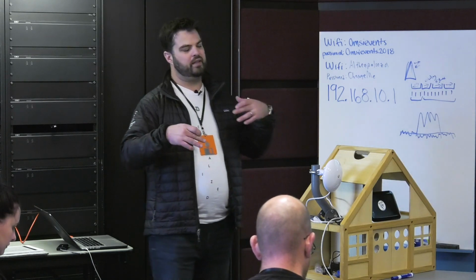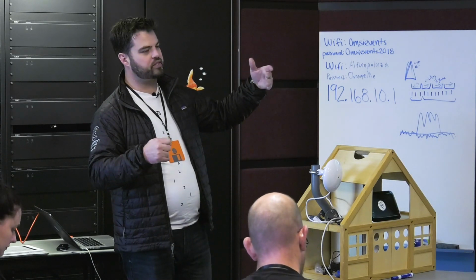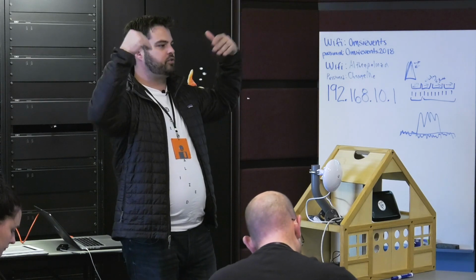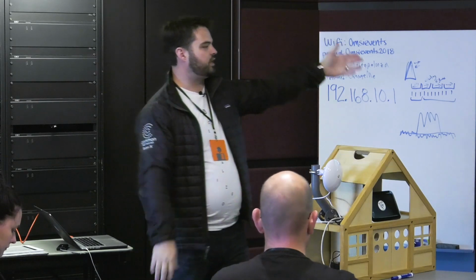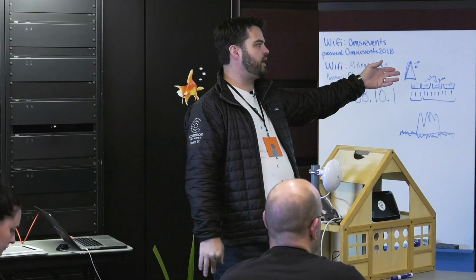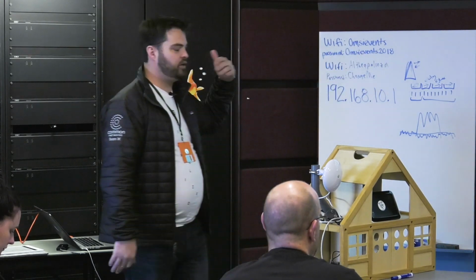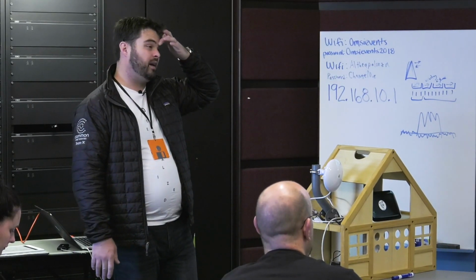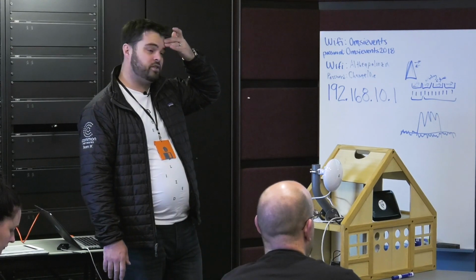Okay, so typically the first thing I do, again, go to the site, figure out how high I want the equipment, make sure there is open space on the tower, check the power situation, make sure there's an open meter bank that I can use, and then go back and start calling the tower company. This is where it does get kind of hard if it's the first tower you've done.